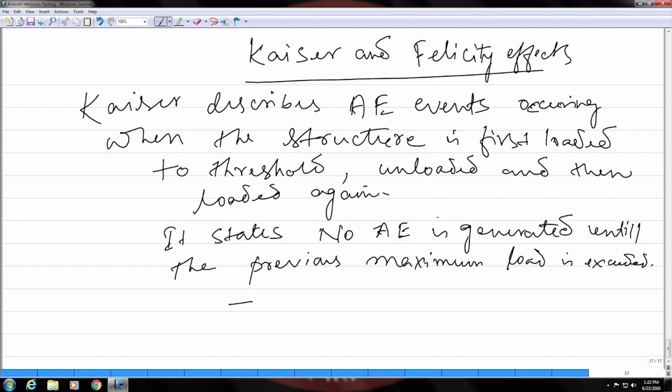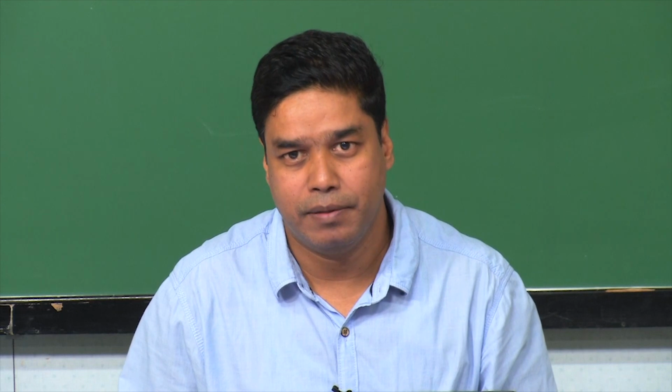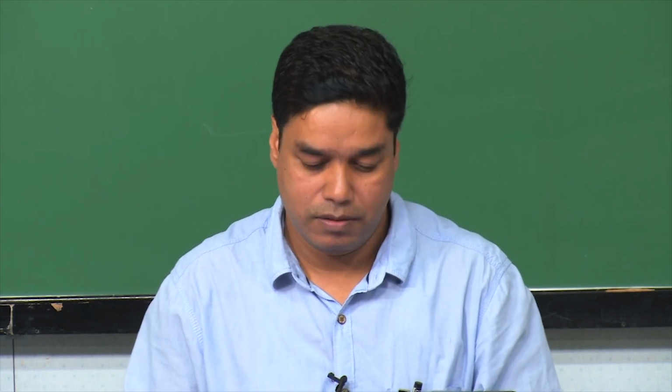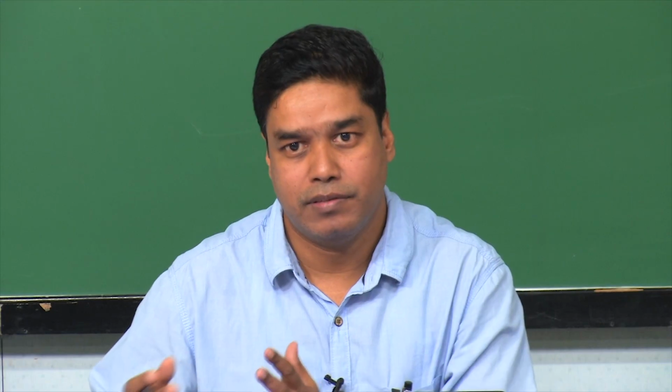Okay. So, that is how you get to know whether the damage is becoming detrimental for the structure or not. Okay. On the other hand, if you see acoustic emission occurring before the previous maximum load, then that will indicate that some kind of damage has happened to the structure which is causing these acoustic emission events.